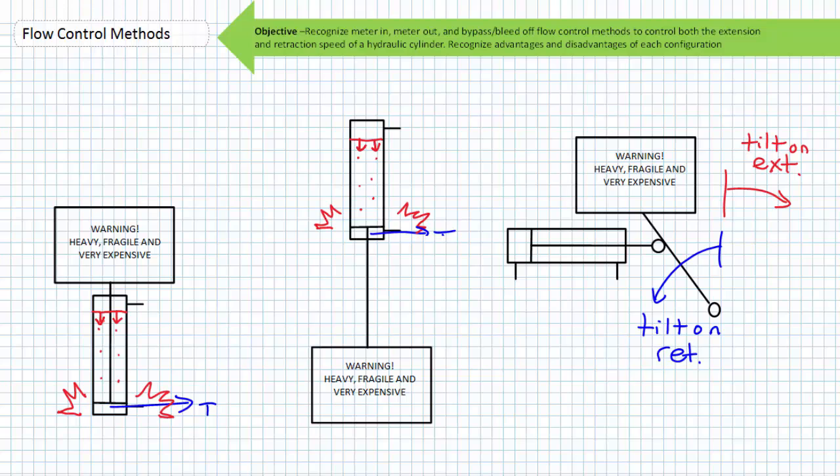As the piston face rips away from this fluid, it creates a rapid depressurization where the fluid leaves its liquid phase and enters the vapor phase, only to be compressed and implode when pressurized flow on the input side finally catches up. This is a cavitation event and will seriously limit the lifetime of your components.